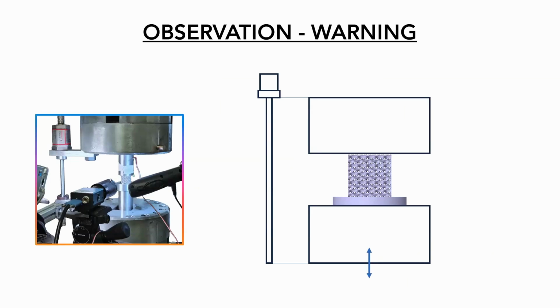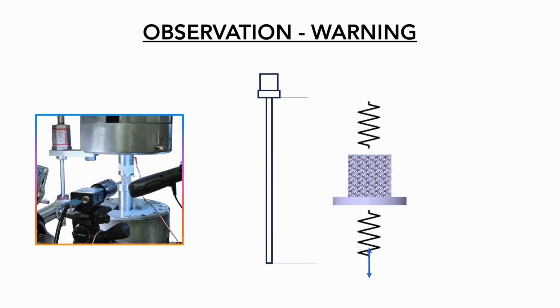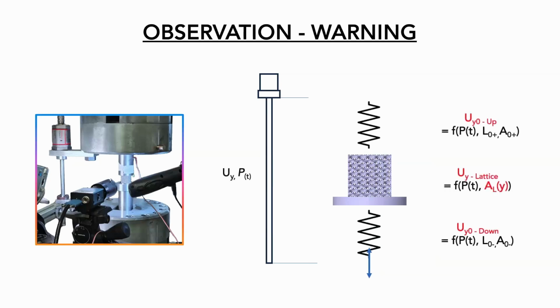So the external sensor can be useful for handling more specimens, but in our case it can be a little bit tricky because we have to handle the stiffness of the clevis. So we handle it with this, because obviously we also have the load registered by the machine.